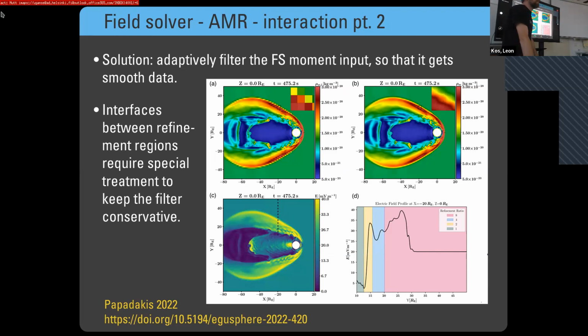So your field solver is not parallelized. Our field solver is parallel. So why does it matter that it has to be the finest mesh? It does not fundamentally matter, but what we really want is we want to fully resolve, or we do the adaptive mesh refinement because we want to fully resolve some areas of interest. That's the physics we're interested in most.